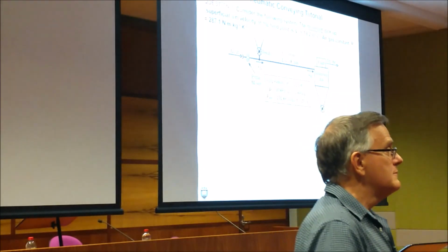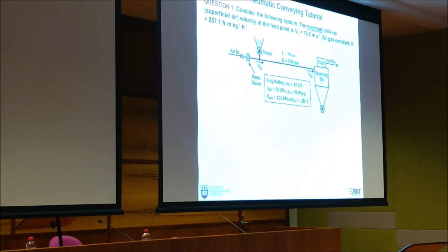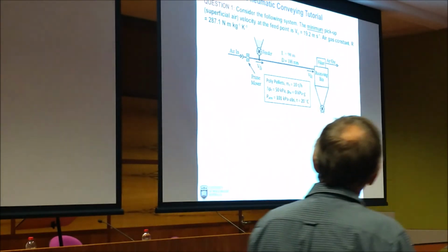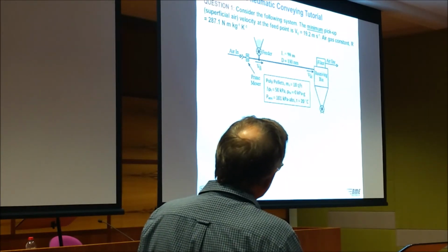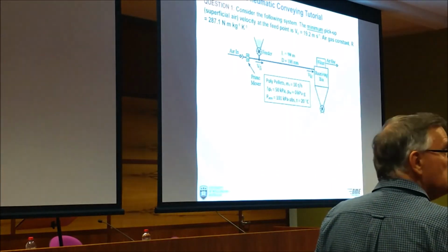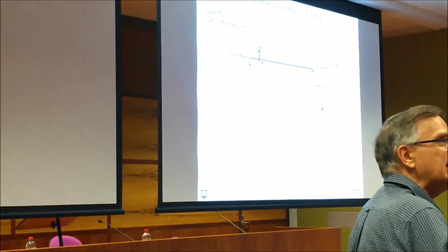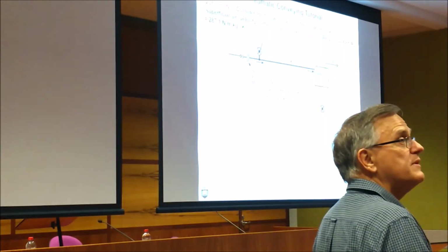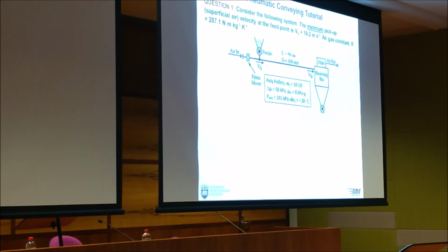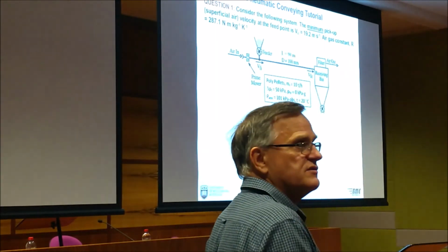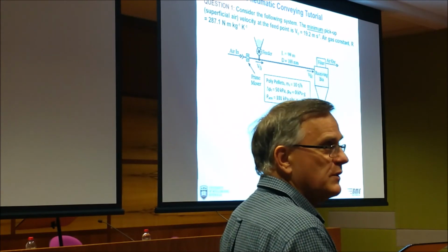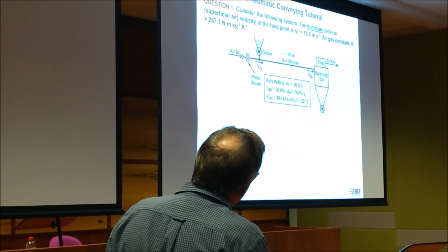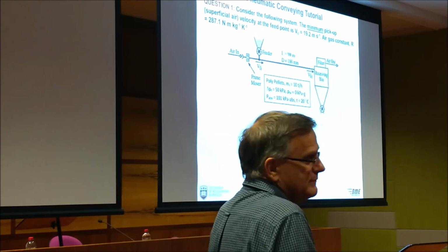What's it going to read, pressure gauge here? Yeah, 50 kilopascals gauge. So 50 minus 0 is 50. That's equal to delta PT. Delta PT equals PFI minus PFE. PFE is 0, so we can ignore filter losses for that system. You can see there, PFE, I even got the answer there, equals 0. I forgot I put the answer there.